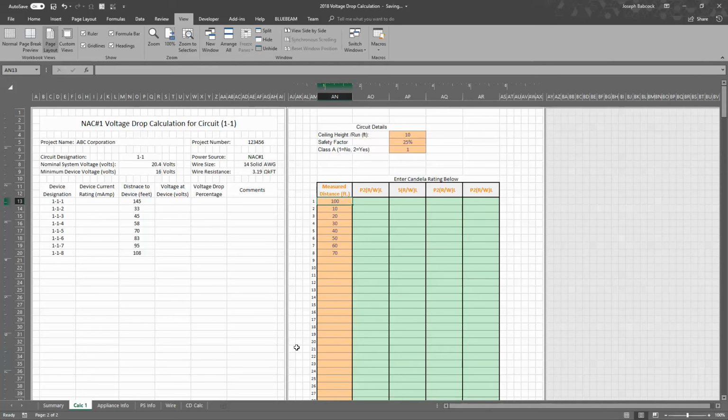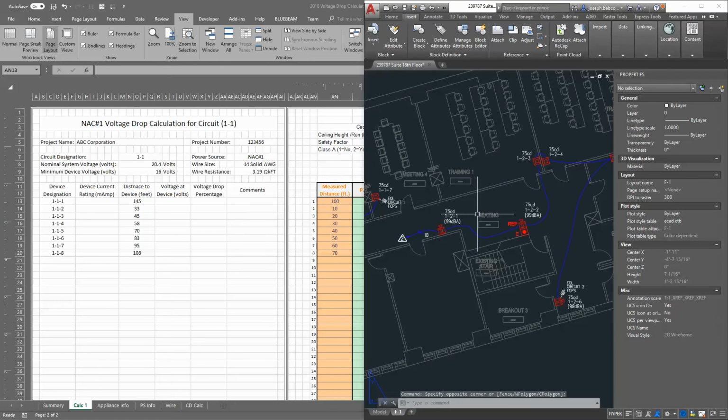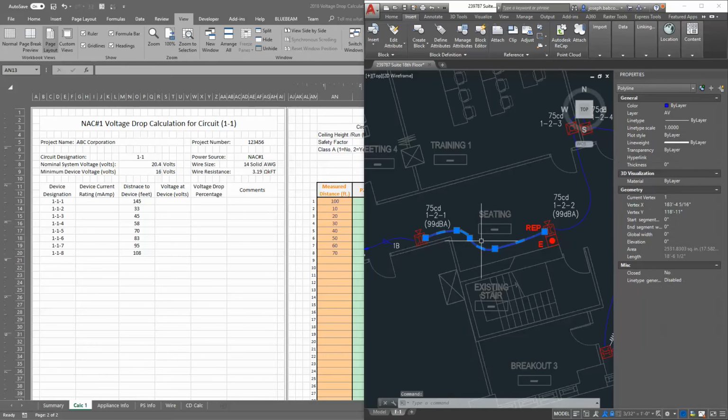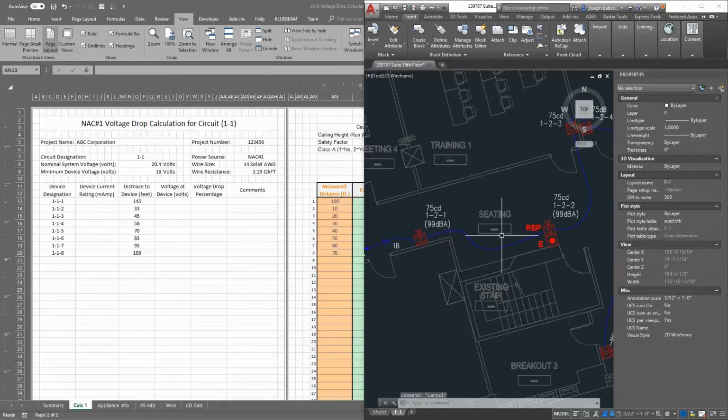One thing you'll notice is I enter a 100 here, and we have a 145 here. Like I was telling you before, when I do just a rough wire length, I'll show you here in CAD, since this is a two-dimensional line, and we know everything's not flat, I typically take this length number and add 10 feet, which would be 28 feet.